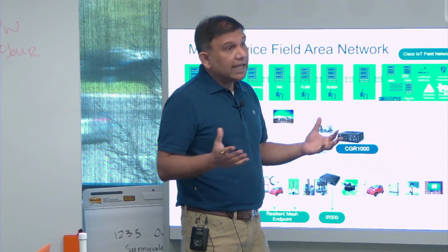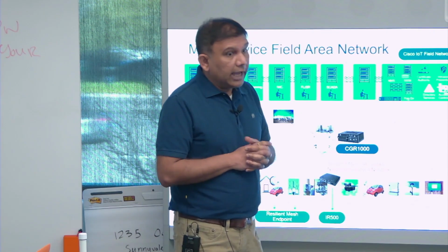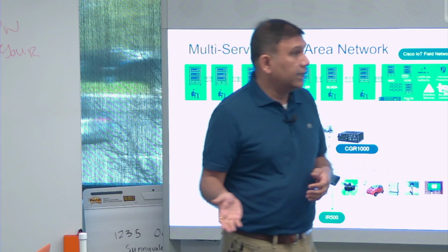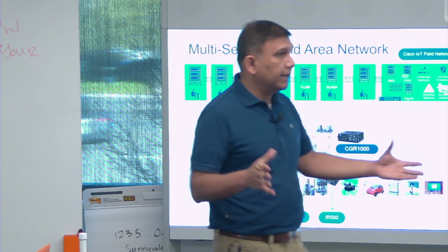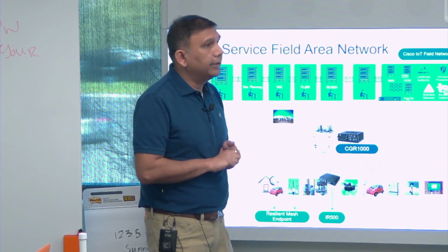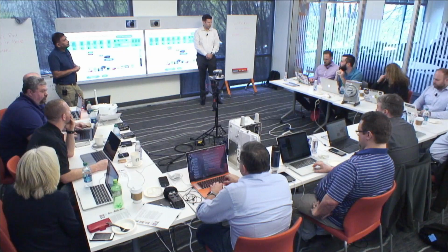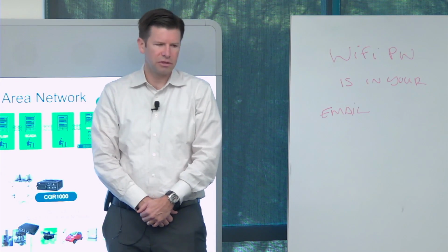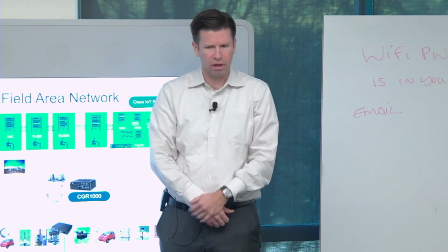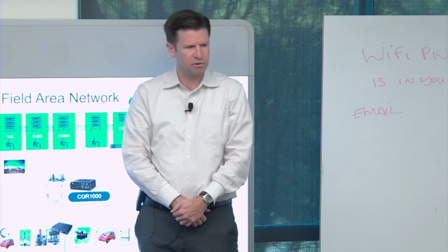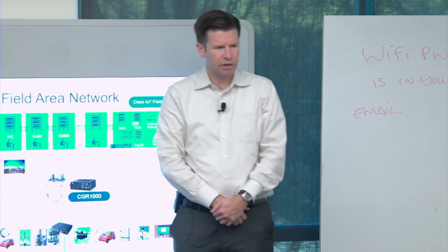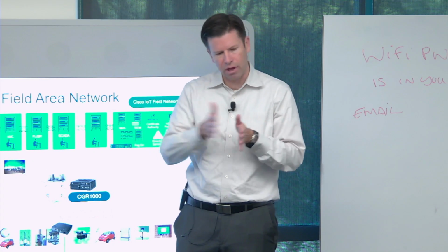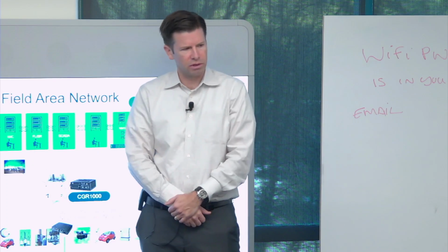So because it's unlicensed, there are interference sources. But compared to, let's say, 2.4 gigahertz, the 900 megahertz is still much less congested. Right, so we do site surveys, looking at both in-band and out-of-band noise. And depending on the environment, if it's near a cellular tower, we do put filters right next to the CGR to filter out-of-band noise. And then within the band, we frequency hop very quickly between different channels.